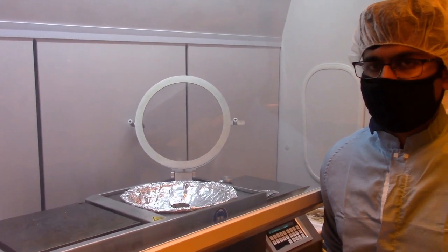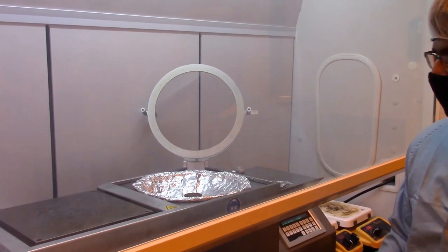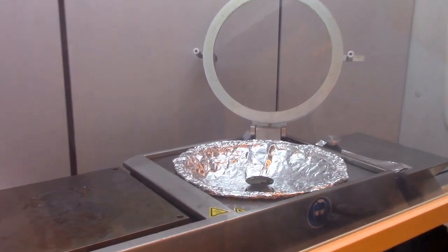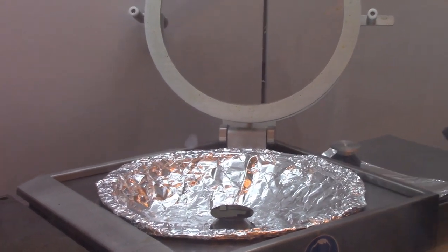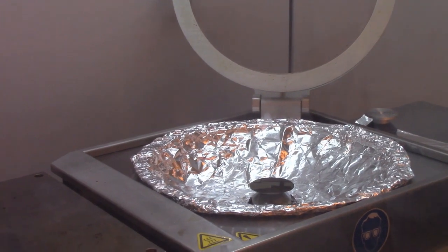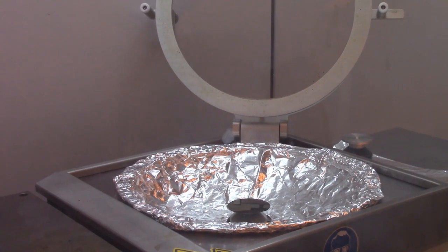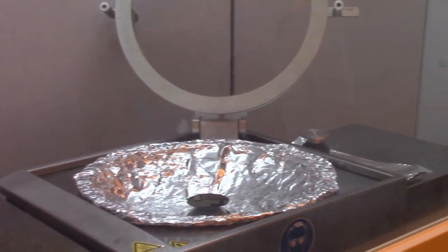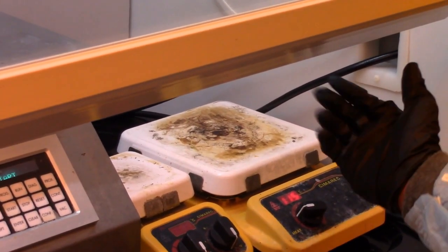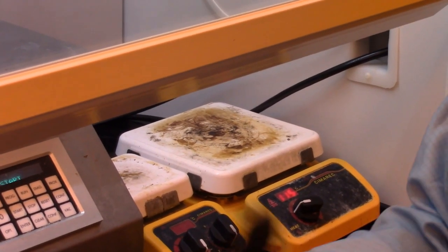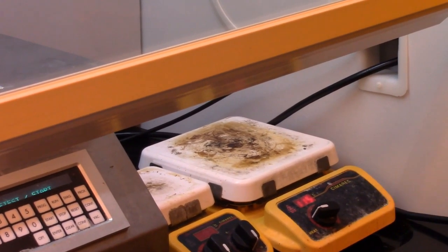To protect the gate oxide on the top side of the wafer, we spin coat using the photoresist. This is a spin coater here, and there are two crucial components to spin coating. One is to spin coat the photoresist on the wafer using a spinner, where the wafer is held using a vacuum chuck and spun at around 5000 RPM. Once the wafer is spun, it is transferred onto a hot plate at 115C for 2 minutes to do a quick soft bake. Since the hydrofluoric acid etch is not an oxidizing etch, we can get away with doing a soft bake if it is for a relatively small amount of time.